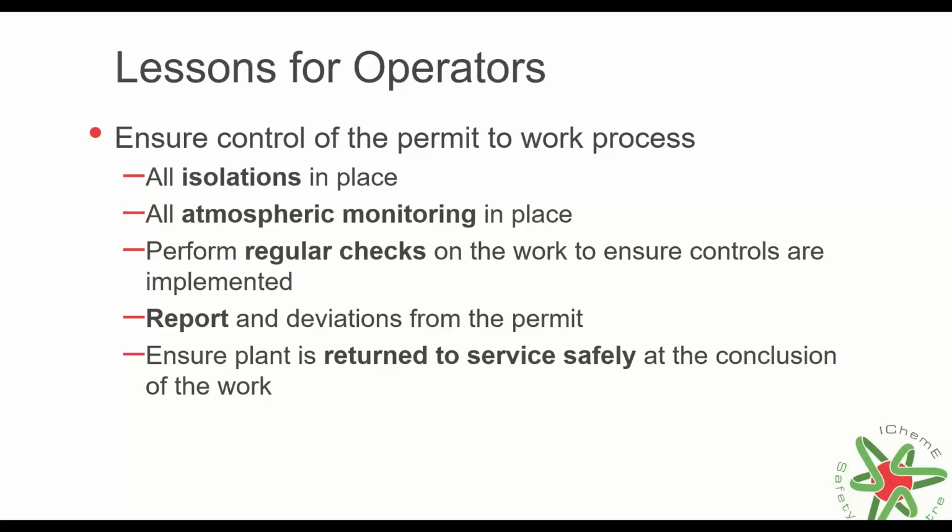All atmospheric monitoring is in place that's necessary. Perform regular checks to make sure that the controls are being implemented. Report any deviations from the permit and ensure that the plant is returned to service safely at the conclusion of the work. And so all these activities do revolve a lot around the idea of your safe system of work or your permit to work process.